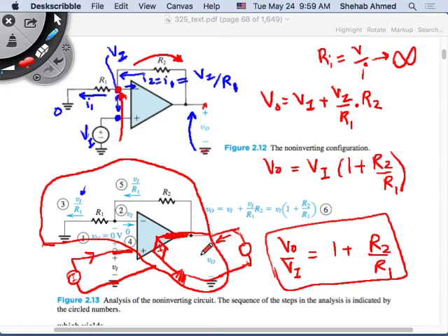If there is current flowing, since there is no input, this voltage source is short circuited. If it's short circuited and I put the voltage source here, a very high current will flow. Ideally speaking, of course, a multimeter cannot provide that. You would have to create an ideal voltage source, not an ohm meter. The ohm meter was the way I used to explain it at the beginning, but an ohm meter would not be able to measure something like that.